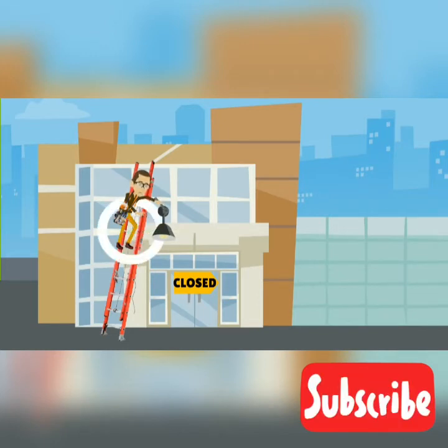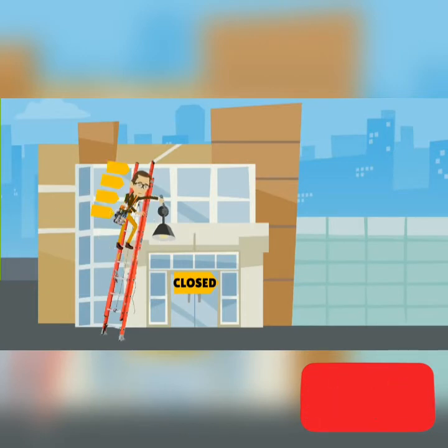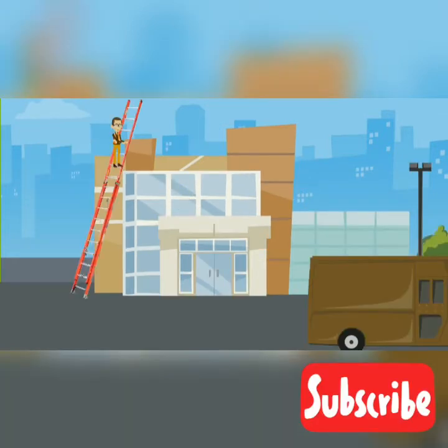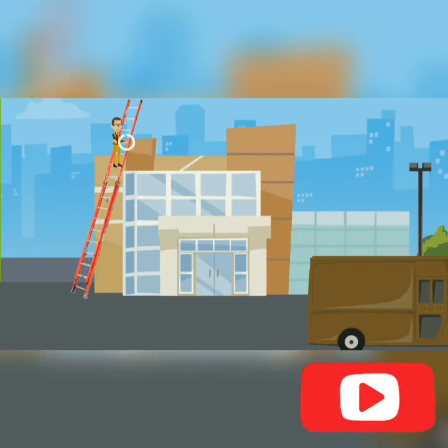When working on a ladder to paint or do other projects, always keep at least one hand on the ladder. Keep your weight centered on the ladder. Don't stand on the top 4 rungs of an extension ladder. Don't overreach to the left or right. When reaching the edge of a landing to step onto, grab the top of the rails with both hands, then carefully step around the ladder.